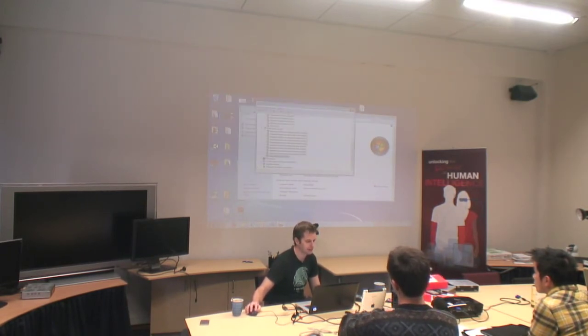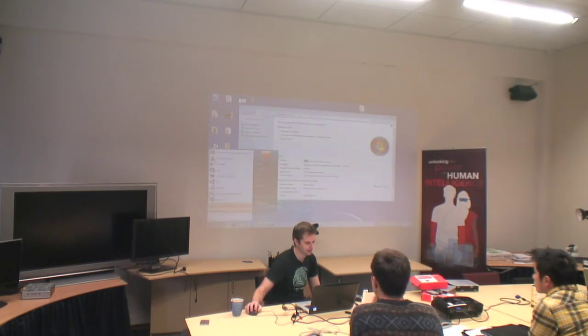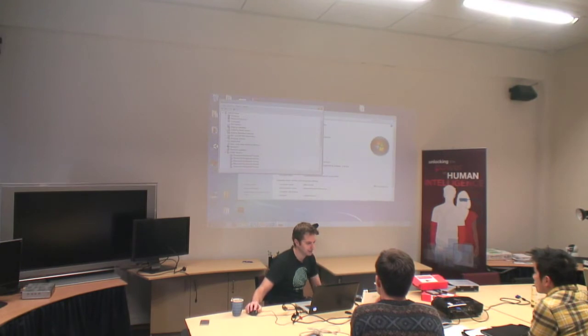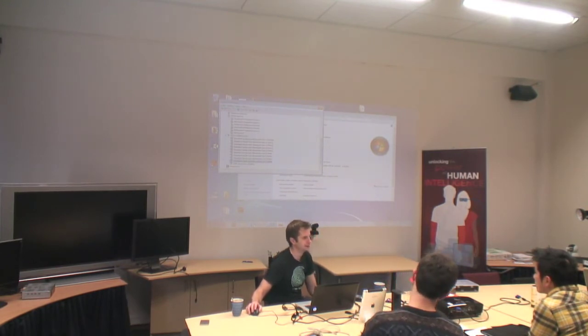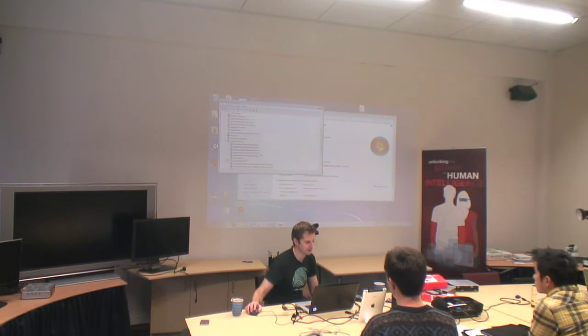But yeah, so basically if you right-click on Computer, go to Properties, and then go to Device Manager, hopefully you should see something which says USB Serial Port on here, and keep an eye, or just make a note of what COM port it attaches to, because you need to know that to program it. For this computer, for some reason, it has like a dozen serial Bluetooth ones, which was actually causing the Arduino software to basically crash. So I've disabled all of that.